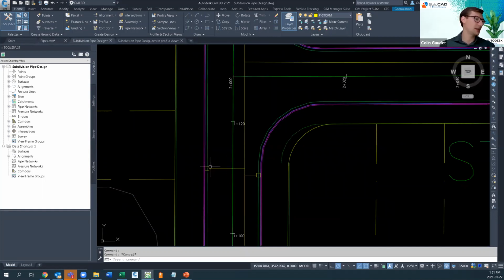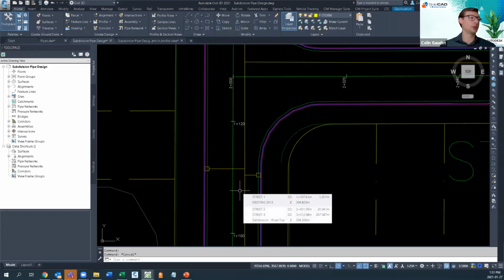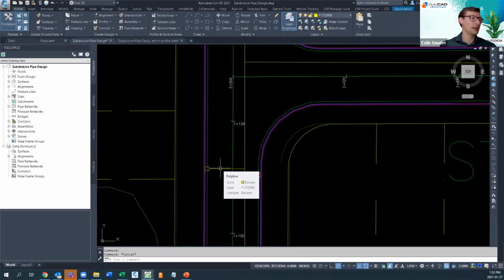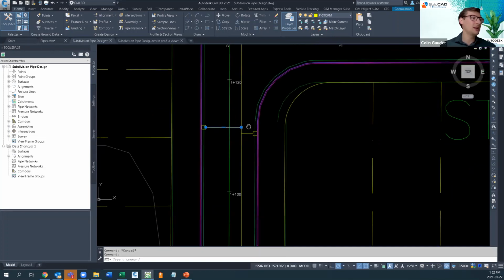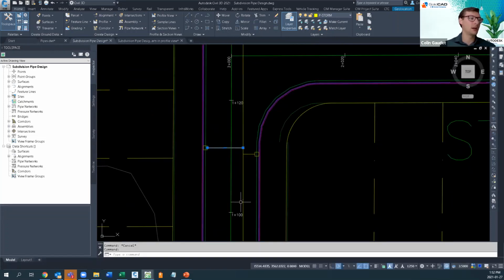Do you sketch them in just like this and they're just polylines? That's one way to do it, but I think we're losing out on a lot of dynamic abilities of Civil 3D if they're just kind of sketched in like that. The other problem though is if I connect this CB lateral into the main line, all of a sudden it severs that main line pipe into two different pieces right there because Civil 3D doesn't handle blind connections well. And then we want to show the invert of this in our profile view.